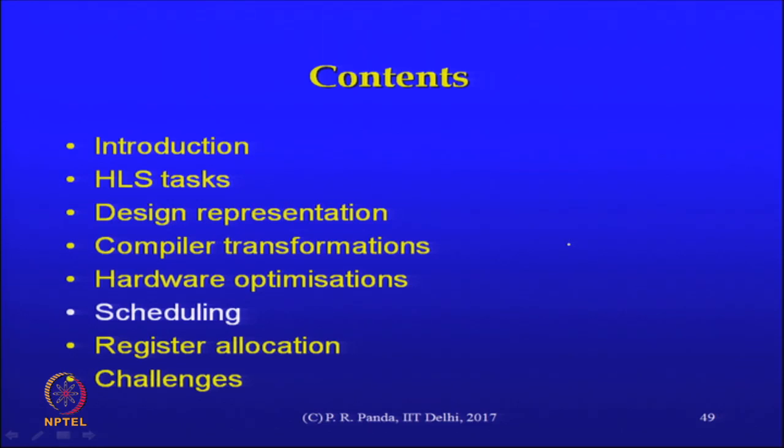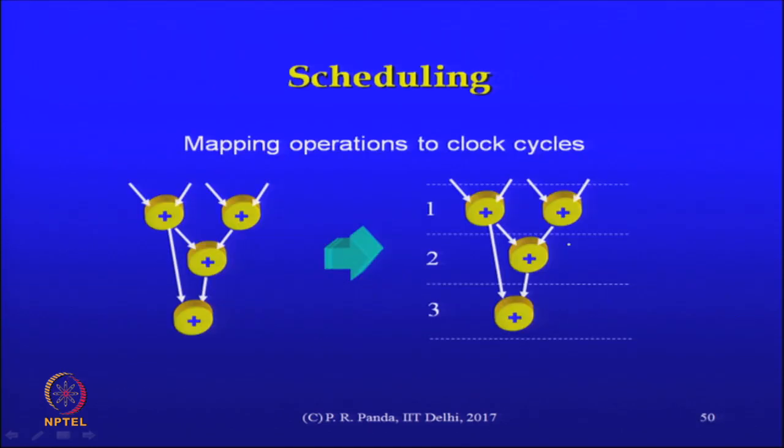The first step, of course, we had identified was scheduling. The point of scheduling is to take us a little closer to the hardware domain, as opposed to that CDFG, which of course is purely functional in nature. There is no timing related information there. Closer to hardware means that first let us introduce some timing partitions, and the result of scheduling visually is just this. These partitions are identified.